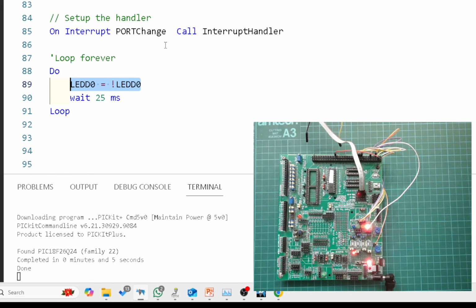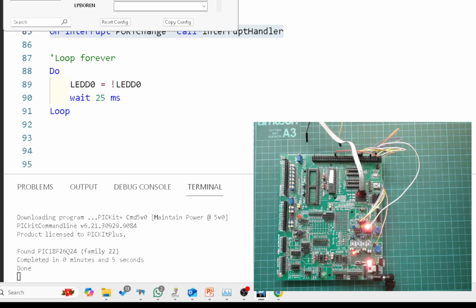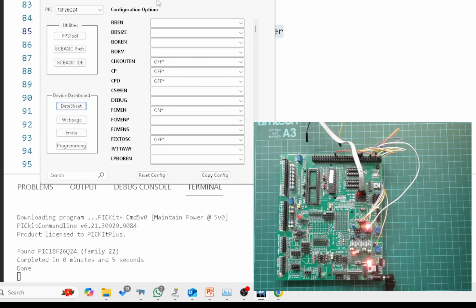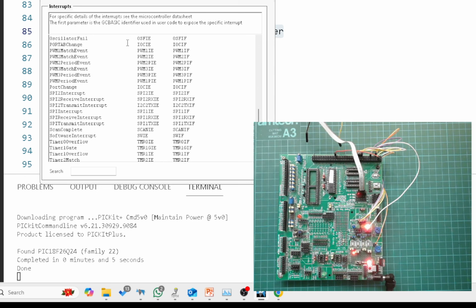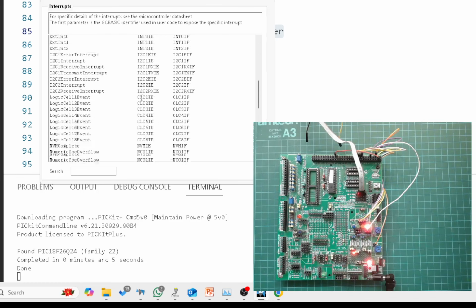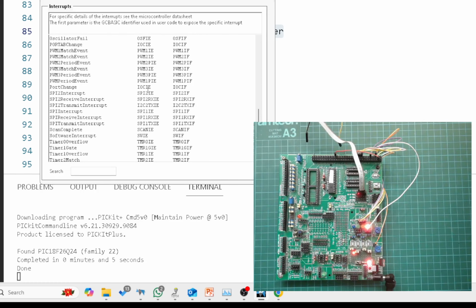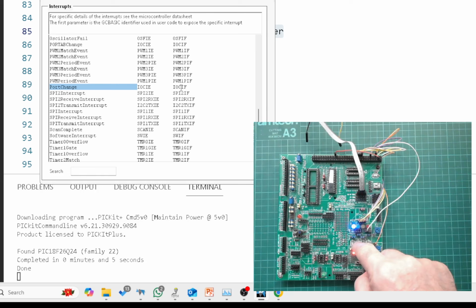Too simple. But what's going on? Well, this command here sets up the global interrupt for you. It sets the registers that we saw inside of here, the register bit, automatically. IOC enable. We saw that before. Here we go, IOC. It sets that automatically. It clears the flag automatically. All you have to do is tell it which edge, and when the event happens, clear that flag. Oh, there we go.